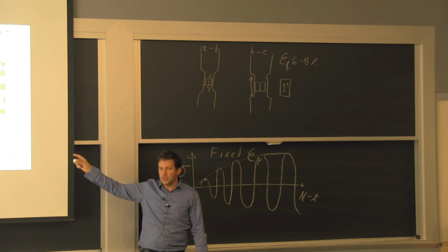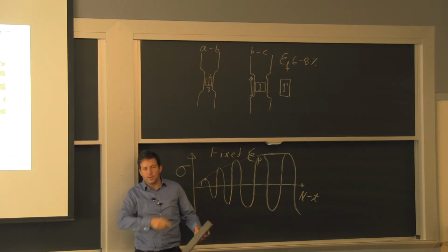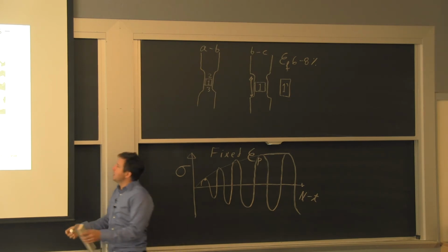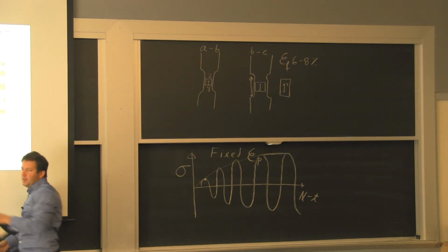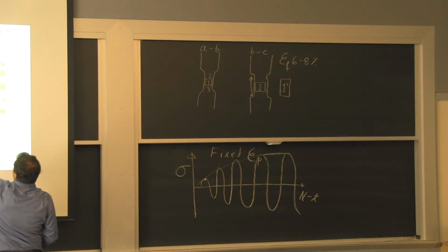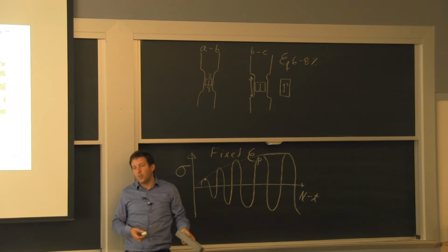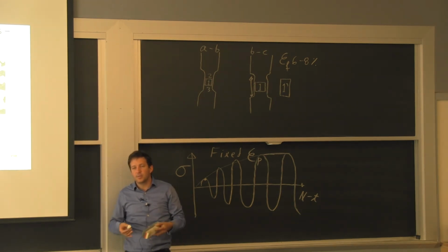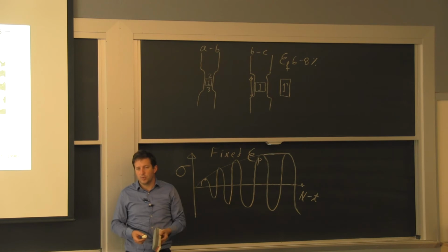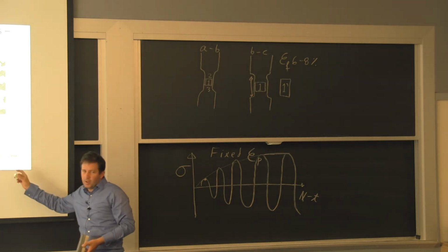Because when you reach these structures where the dislocations, oh, you have more energy, okay, I'll give you one more. I just have enough because I created these zones that are filled with defects. And what it takes to go from one side to the other is just to bend enough based on the size of this area. So the stress, you still need the load, but from one time to the other, the structure stays the same. So if you come with the same load, you get the same strain, and it becomes stable. Now, I'm mentioning it in terms of cyclic deformation.